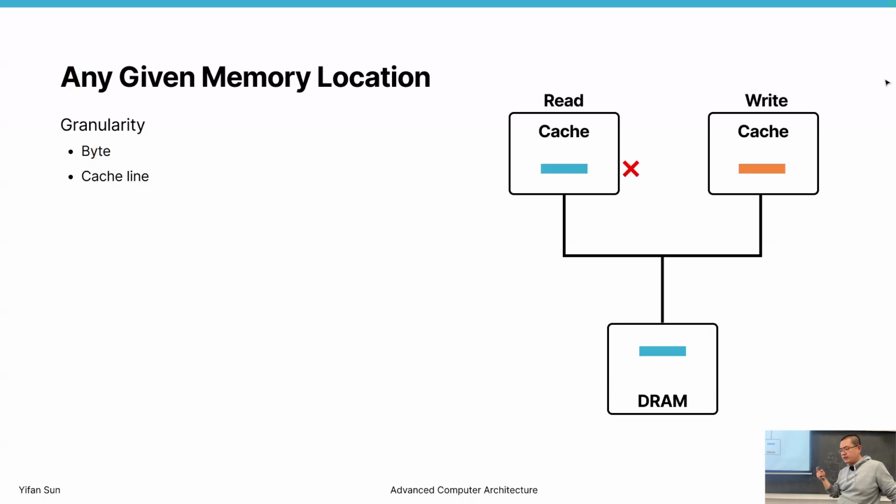Although there are still many different variations of cache design where you can hybridize some CPU and GPU design decisions. You can even do something like, oh, part of this cache line is valid, the other part of this cache line is not valid. These are also something that is totally possible in CPU design.